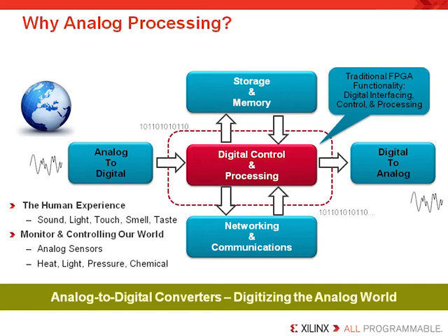Xilinx has provided the system monitor capabilities on our high-end FPGAs for several generations with an eye toward monitoring power and voltage. Our customers demand more, so we improved the system monitor by doubling the number of ADCs and improving each ADC's sample rate by a factor of 10. This updated analog interface is referred to as the Xilinx Analog to Digital Converter Module, or XADC core for short.